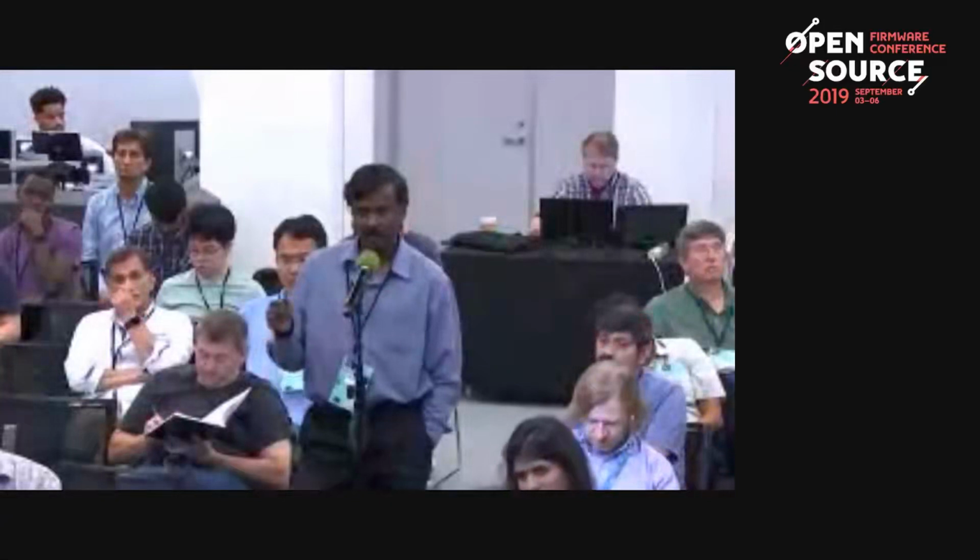If you remember last OCP Summit in Amsterdam, we demoed a 5-second warm reset and a 10-second cold reset on an OCP server platform. And again, we took a lot of things out of the DXE phase, things that you have platform dependency on, for example, BMC. But waiting for the BMC to come up takes 20 seconds on a cold boot, so you have to wait for that. IPMI commands take a lot longer. If you strip everything down to the bare minimum required, I can bring it down to 5 seconds and we demo it. But I think you're supporting my argument.